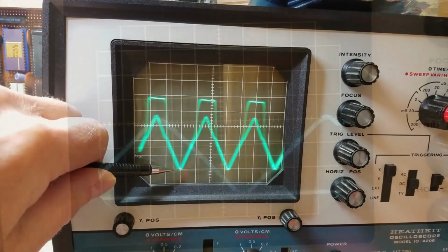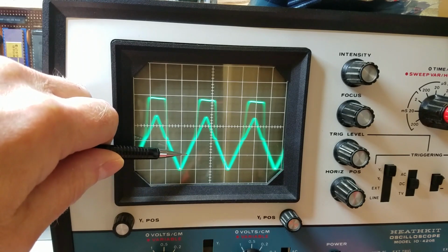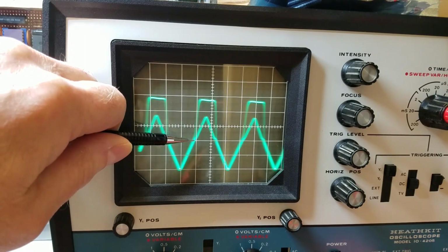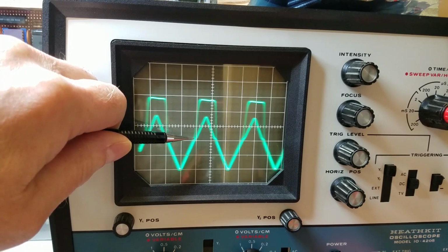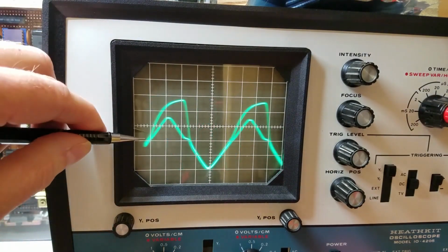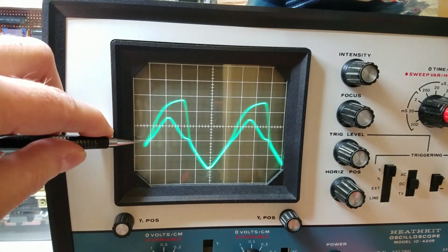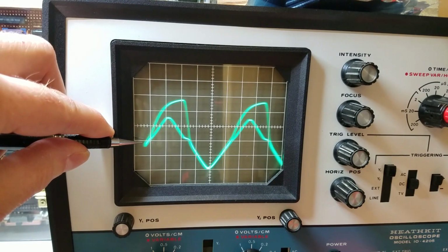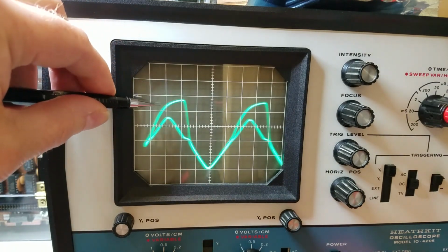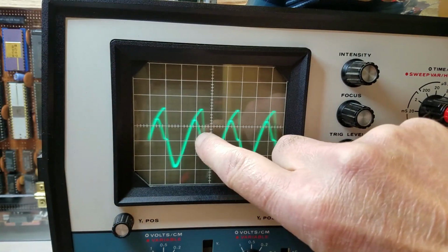First, I set it to about 14 kHz so we can examine the switching points in detail. You can see that a low level voltage of about 2.5 volts switches the 5 volt side. Next, we increase the frequency to about 80 kHz, and we can start to see some slower rise times on the 5 volt side. However, the rise times are less than 2 microseconds, which is more than fast enough for communicating with the 6502 with a 1 MHz clock speed.